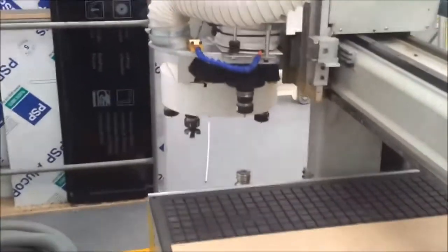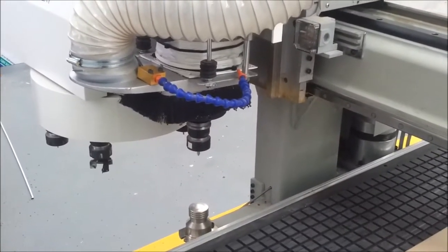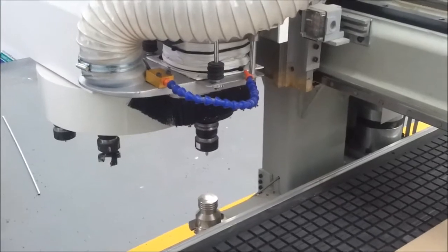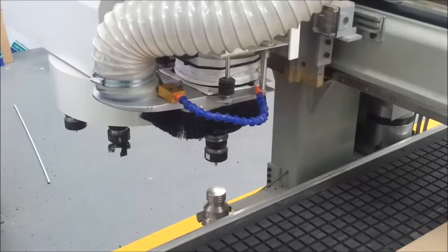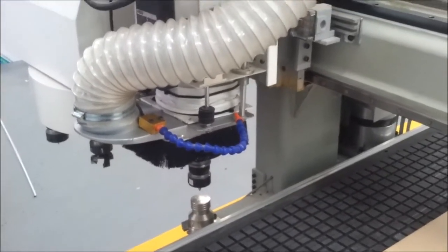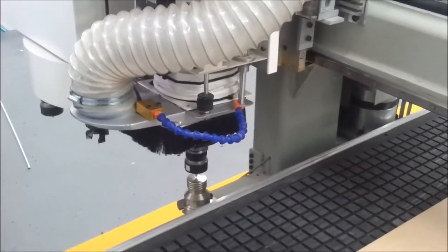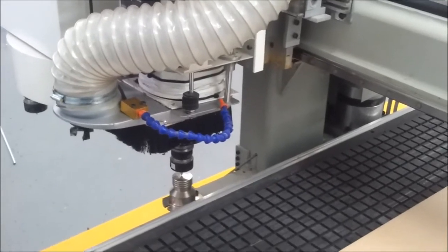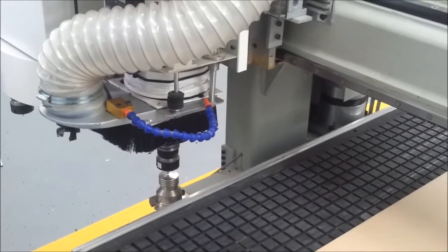So I'll click the cycle start, and you'll see it runs across, and it very slowly goes down to do the auto tool touch off on my touch tab. Now what this will do at this stage is it'll actually give me a measurement for that reference offset, the Z offset, the one that we were just looking at that had the really strange 187 number in it. It'll actually measure it and check it, and when it does, I can show you where you get that reference from.